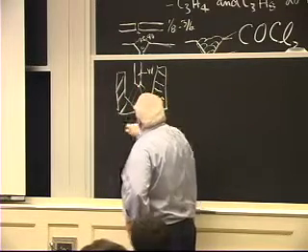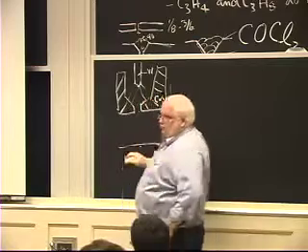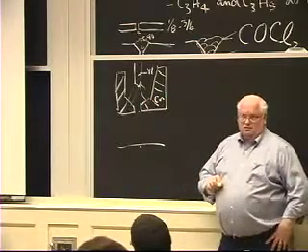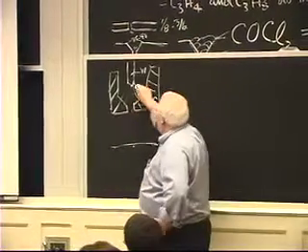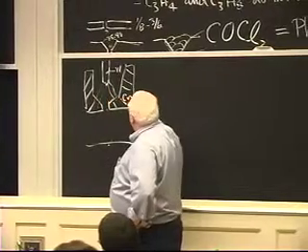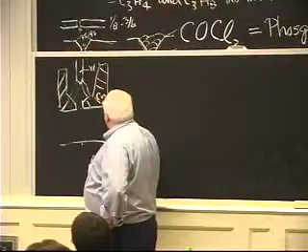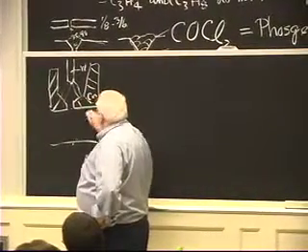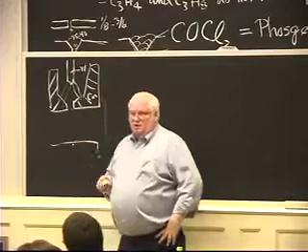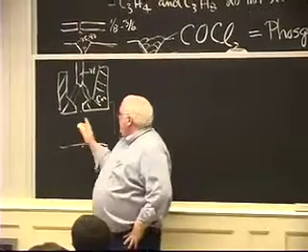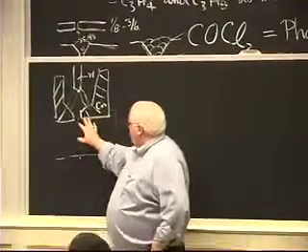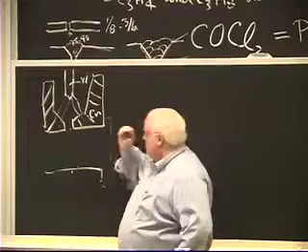It's not next to the workpiece necessarily, okay? And this is called the non-transferred arc, because the arc is not transferred to the workpiece. If a portion of the current is carried to the workpiece, then it's called a transferred arc, and I'll talk about those later.